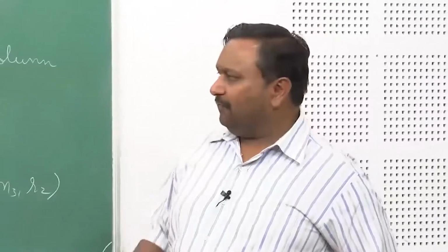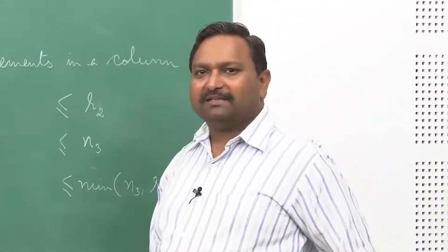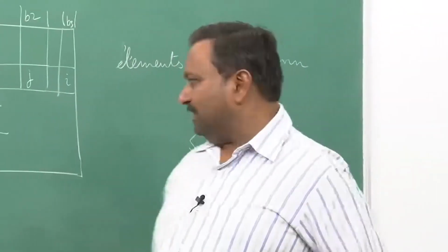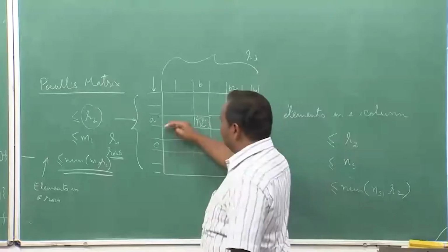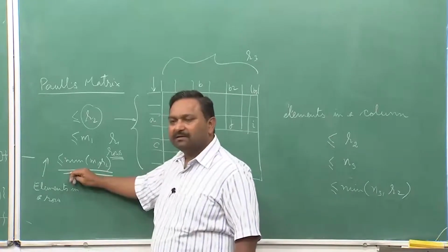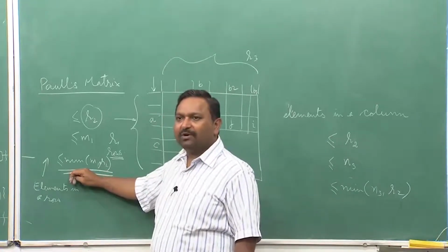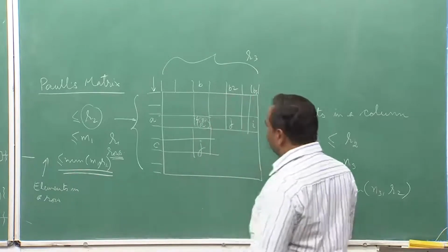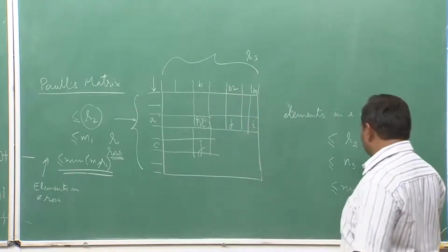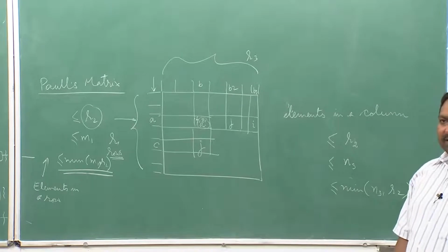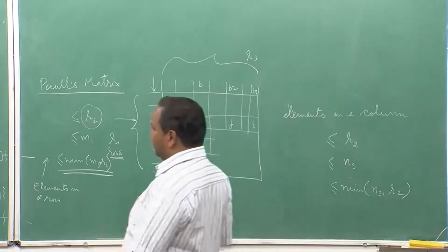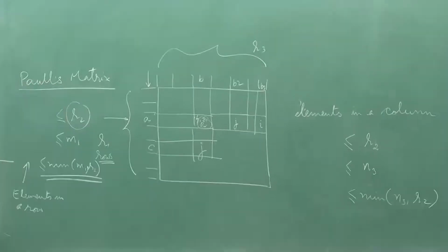Now, if you look at a pulse matrix, can you identify whether it is correct or not correct? So, one thing which is sure, if my number of elements here are more than this, then there is certainly a problem, it is not correct. Or if the number of elements in a column is more than this, then there is a problem. Okay. So, let us write down the legitimacy conditions for the pulse matrix. We will use this pulse matrix in all of my theorems to figure out the conditions for strictly non-blocking nature and rearrangeably non-blocking nature.